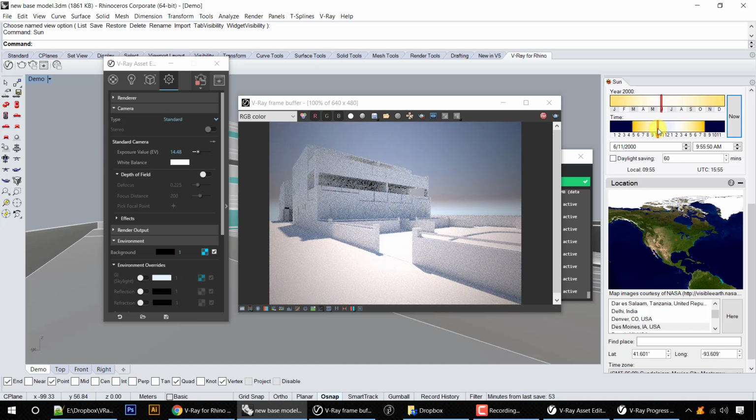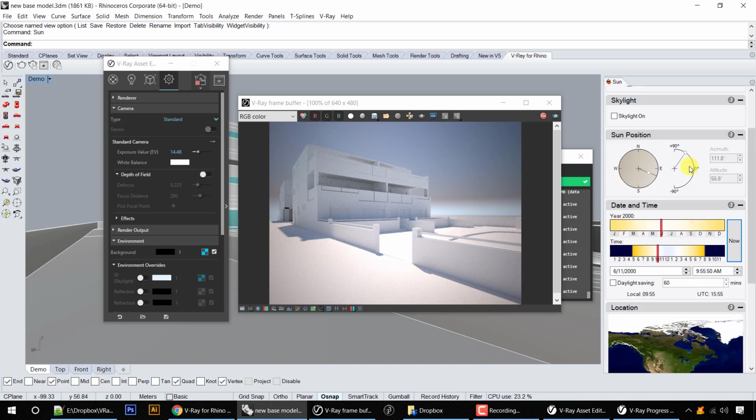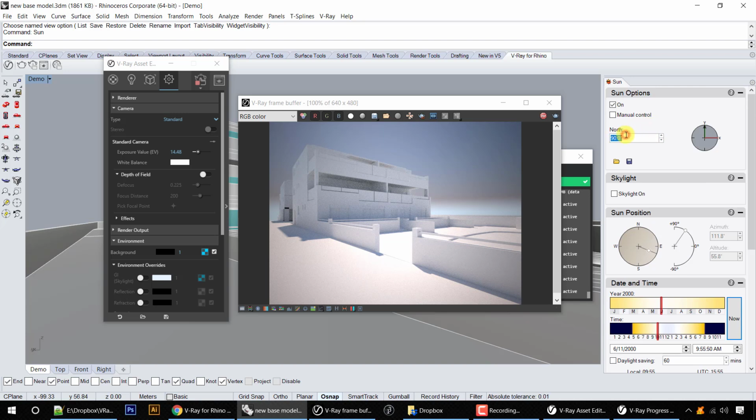So when you're trying to represent the building though, or your space, or your project, you gotta think about the look. Make sure you get the north arrow correct. So in this case, it's 90 degrees. So if you're looking at the plan view, 90 degrees is up. That's typically what most of our projects will be modeled at. But you really got to be careful that that's correct, right? That your building's actually oriented correctly. Otherwise, these settings are not going to work.